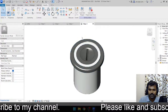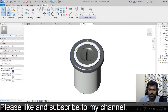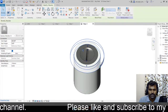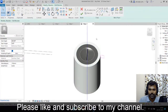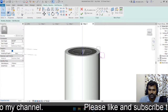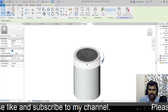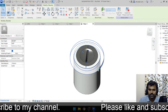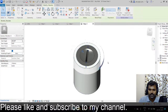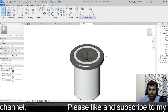Nice. So I have done this keyhole as a separate family in a generic model. Everything is an extrusion or sweep or revolve. I think this piece is actually a revolve. If I go to edit revolve, you can see I have taken the center axis and I have taken this profile. Okay, so when you finish, it looks like a face. I don't know what it is called, so I don't know, whatever you call.